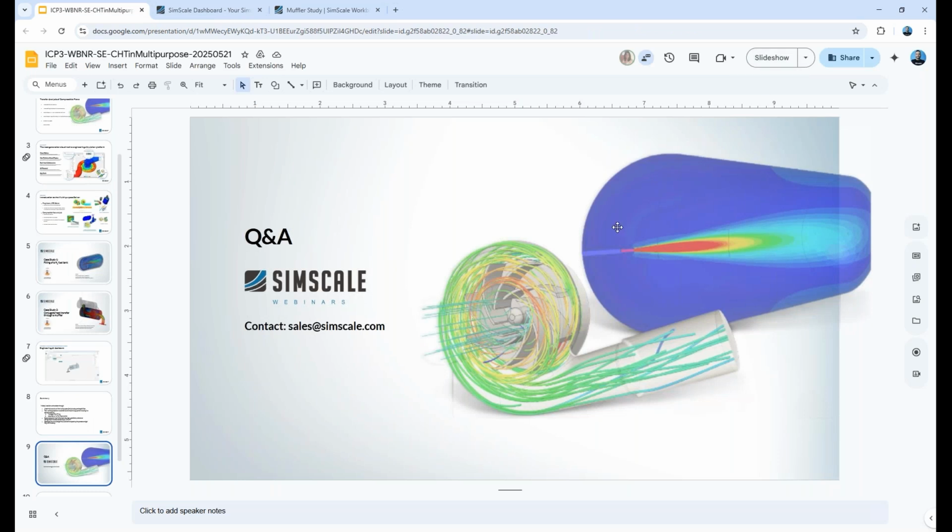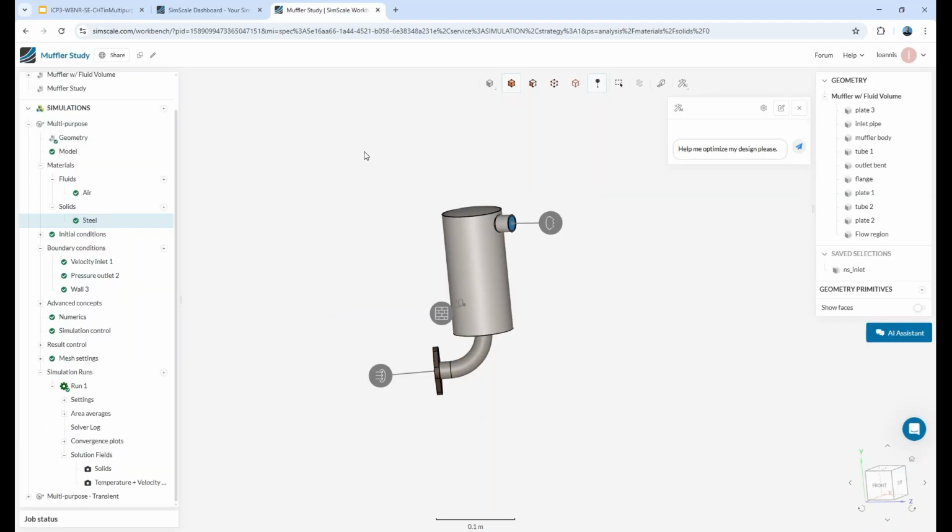What is the accuracy rate from creation to actual as-built operation? I am assuming this is a question around the accuracy of the solver. If not, then please let me know. Typically, we have validated the solver anywhere between 2 to 5% accuracy with test data. For example, a transonic compressor generating the full performance map lands us below 5% of actual test data.